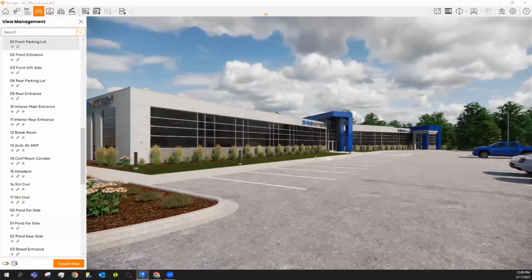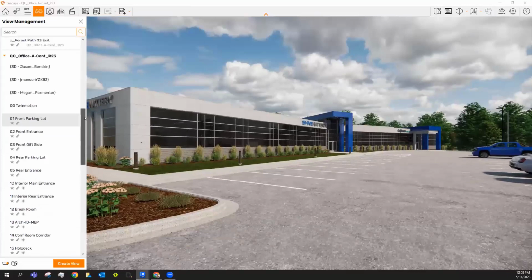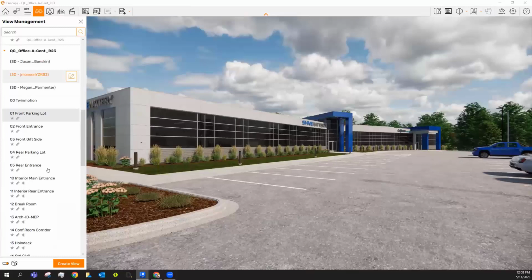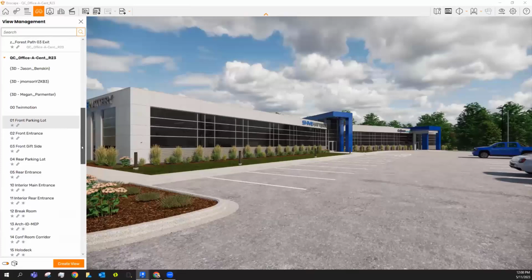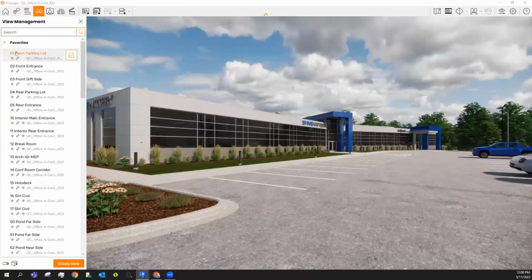And one benefit you can get from these visual presets is they can start to be tied into your view management system. When you first open view management, it opens all the cluttered views from your Revit file. We can create new views from this, or we can edit these. When we edit them, we can favorite them. And part of them being favorites is getting them into an organized tour.